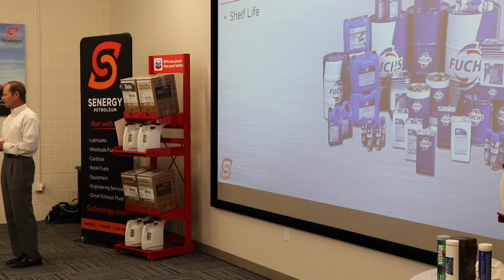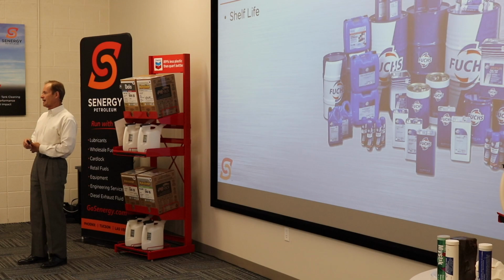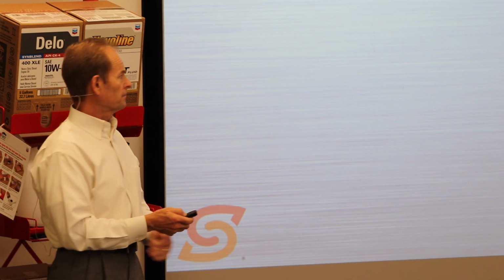And oil, most oils, pretty robust. I mean, we're talking 5 years, 8 years, something like that. Oils can last a long time. Greases, not as much. If you've got a 3-year-old grease, you might want to take a look at it. One thing we can do is send a sample out to be tested and make sure it's okay. So keep an eye that shelf life on grease is shorter than oil.